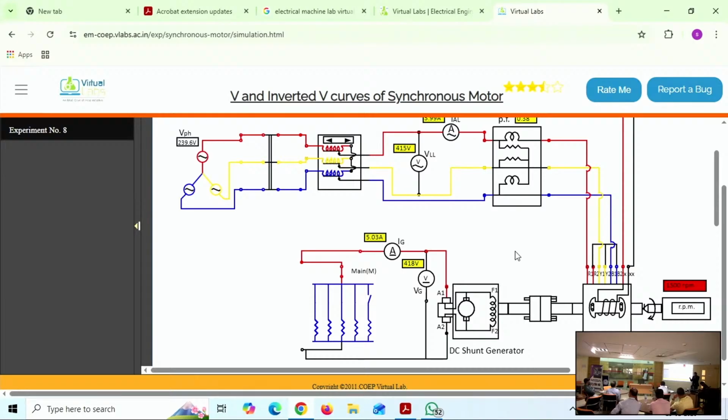While we are applying load to the synchronous motor, because of this, what phenomenon? It makes so much noise, right? It creates so much trouble handling loaded synchronous motors with respect to damping and what do you call that? Hunting. Yes. Because of that, loading of the synchronous motor is not smooth. I will show you the rotor angle.